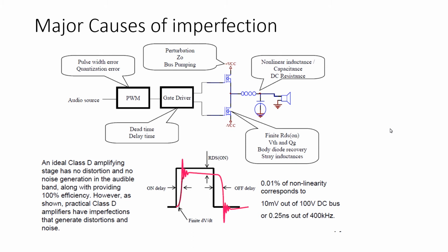In practice, this process is rather complicated and you need to provide a number of high tolerance electronic blocks. There are errors due to the finite MOSFET switching performance. There are errors due to the output filter nonlinearities. And there is the bus pumping effect where switching MOSFETs work as voltage multipliers. For details, read manufacturers' white papers where the physical processes and remedies are well described.